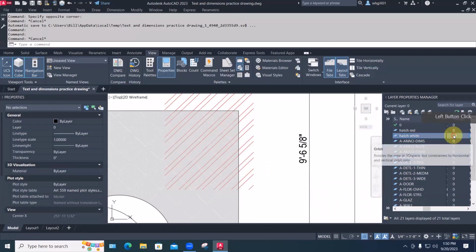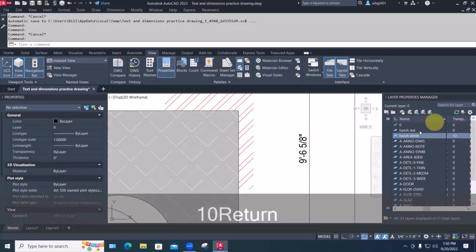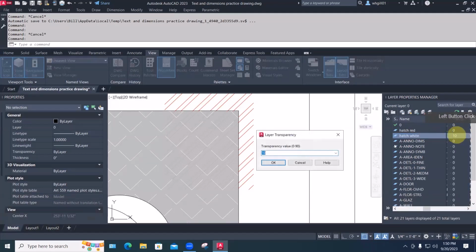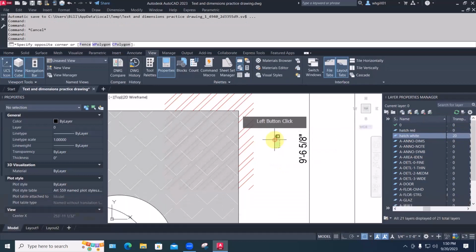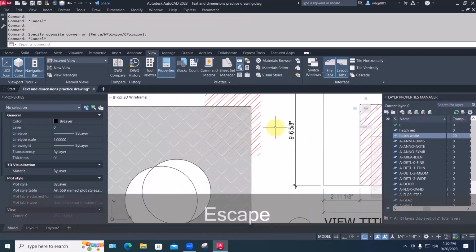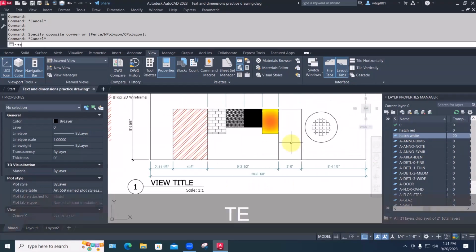Maybe I'll change that to transparency being only 10. Maybe a little more, 20. So with all objects, not just hatches, we have those options of stacking, i.e. draw order, and transparency or opacity that you can use for whatever design kind of things that you want to do. Let's talk about how text and hatches interact.